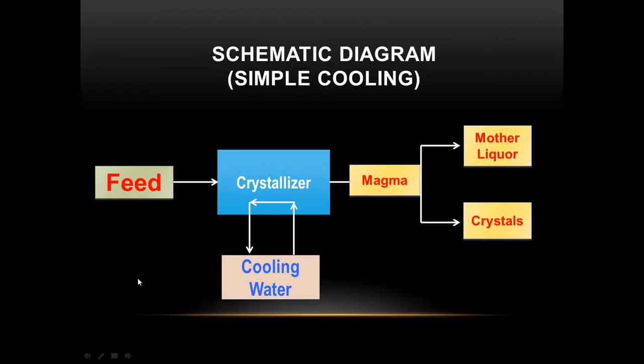So this is a case of the formation of crystals induced by a simple process of cooling down your feed in a crystallizer. These crystallizers in their simplest forms may look like cylindrical tanks oriented horizontally, divided into two parts. It's a half cylinder, and in that half cylinder, you have rotating coils where cooling water is flowing in the process, inducing cooling of your